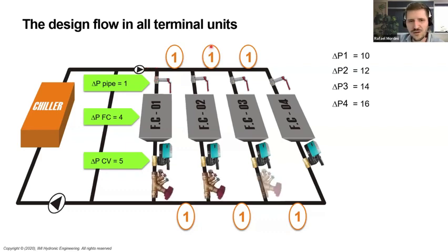So our goal here is to install the balancing valves. You see them here on the return. This is one picture of what could be any balancing valve. As we are adding balancing valves, we are adding something to the system. Every single valve or accessory represents a pressure drop for the system. So let's consider for the fan coil number 4 here, the circuit 4, this valve will create 1 foot of pressure drop for us.